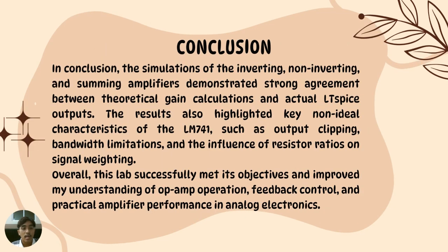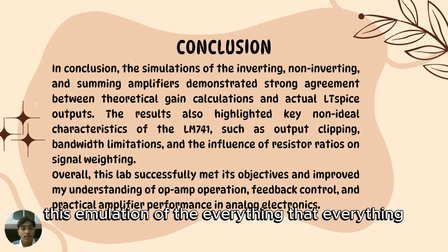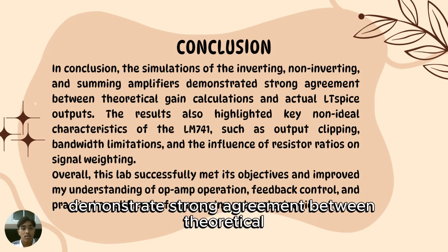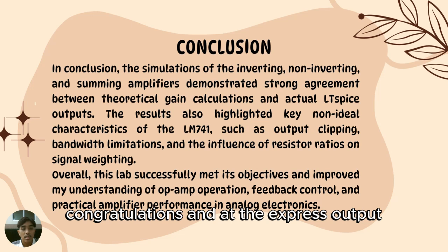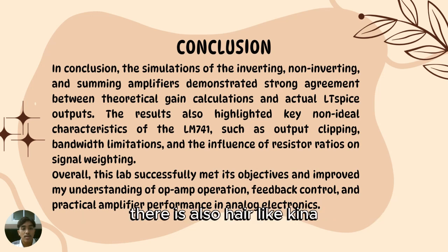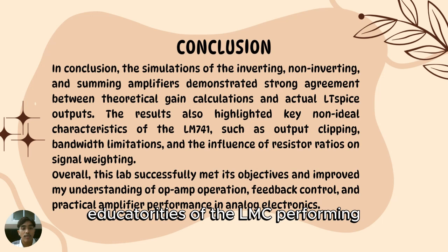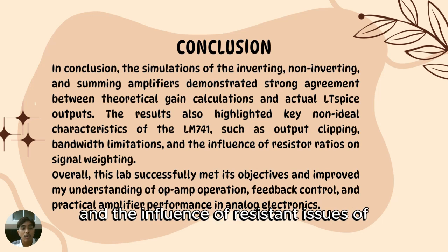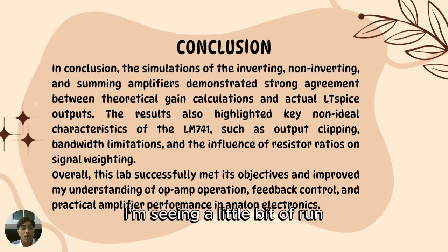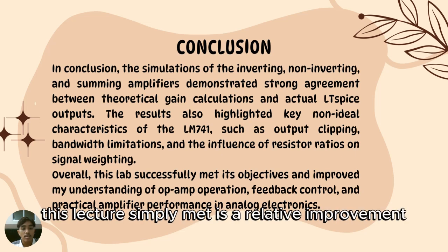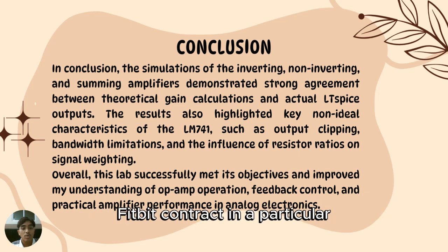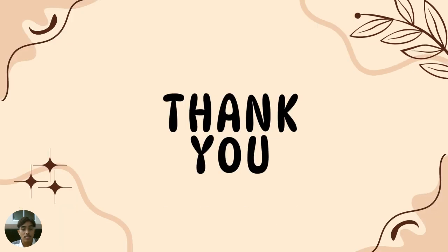For conclusion, the simulation of the inverting, non-inverting, and summing amplifiers demonstrates strong agreement between theoretical gain calculation and actual LTspice output. The results also highlight key non-ideal characteristics of the LM741, such as output clipping, bandwidth limitation, and the influence of resistor ratios on signal weighting. Overall, this lab successfully met its objective, and improved my understanding of op-amp operation, feedback control, and practical amplifier performance in analog electronics. That's all from me.